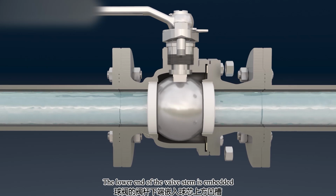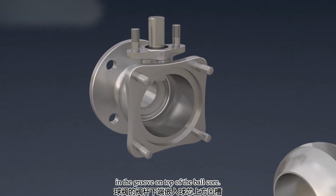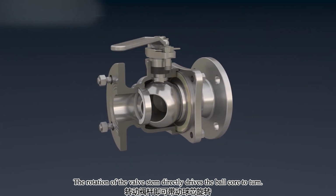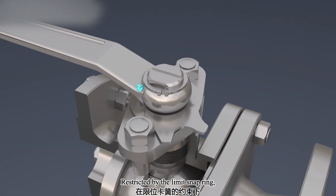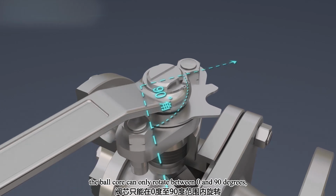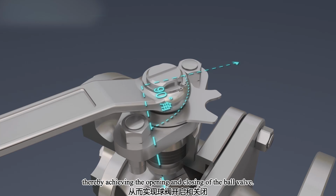The lower end of the valve stem is embedded in the groove on top of the ball core. The rotation of the valve stem directly drives the ball core to turn, restricted by the limit snap ring. The ball core can only rotate between 0 and 90 degrees, thereby achieving the opening and closing of the ball valve.